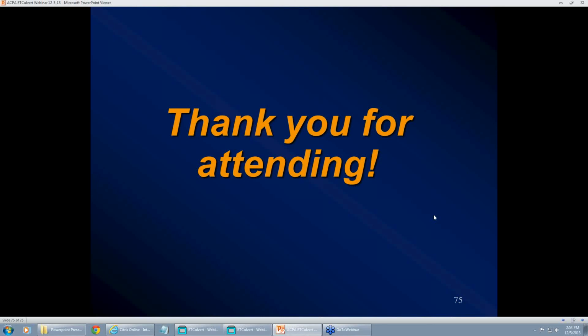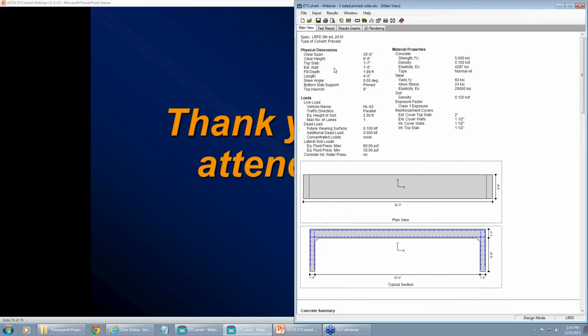Also, what edition of AASHTO LRFD? It's good up to the 5th edition. Yeah, because there's only one small change to the 6th edition that affected culvert design. The only thing that's different, I believe, is the cracking moment, but that shouldn't really affect your design too much. Okay.